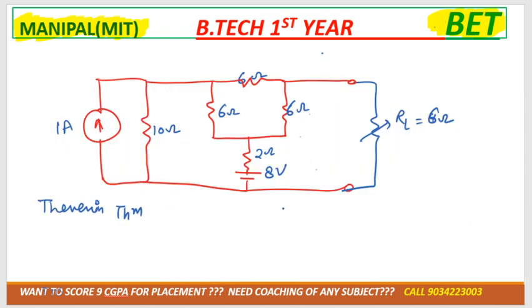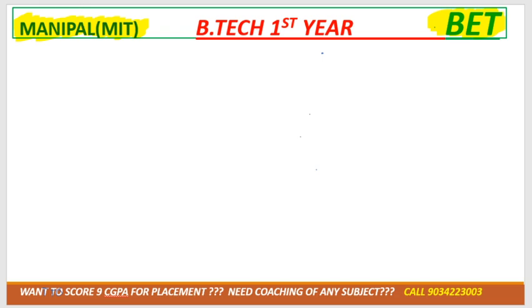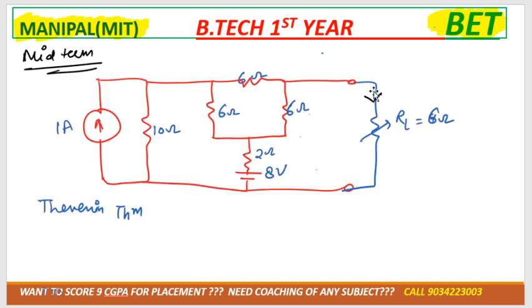Now see, this is your question from your midterm paper 2024. Okay. So in this, what we need to do is calculate the current across RL by using Thevenin theorem. Okay? So see, in the Thevenin theorem, what we basically need to do is calculate the current, and what is the formula for current? That is VTH divided by RTH plus RL. Okay? For this we need to calculate two things, VTH and RTH.